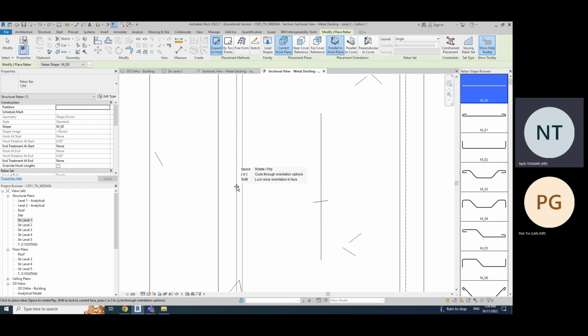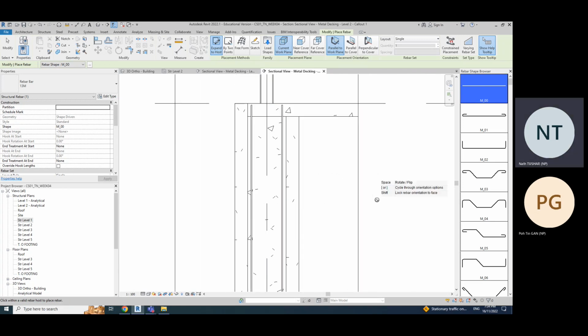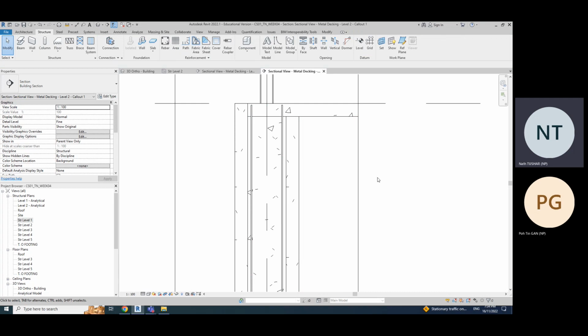If you try moving beyond that green line, your cursor will turn something like that. So bring it back, it will snap, select, and your rebar will appear. Okay, try doing that. This should take a little bit of getting used to, but it's important that you figure that out. Try that, guys.